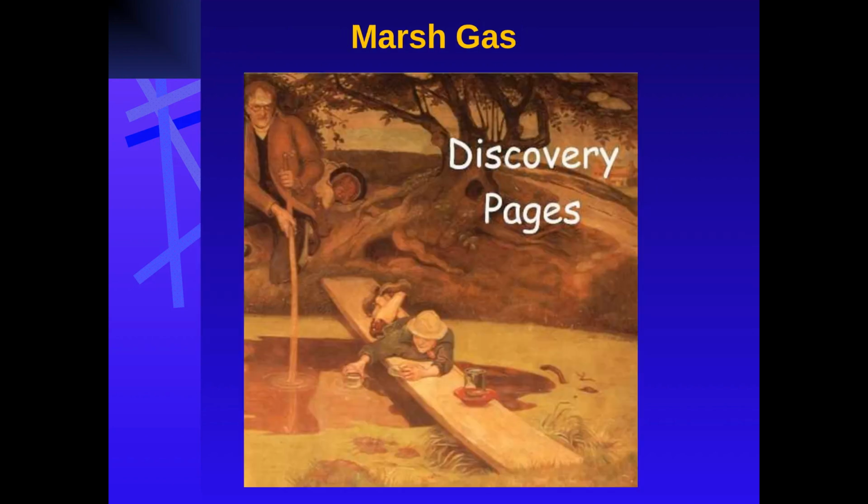Aerobic treatment, while effective, has several disadvantages. It is an energy-intensive process, primarily due to the need for continuous aeration. It also produces large volumes of sludge, which requires further treatment and disposal, adding to the overall operational cost. Moreover, aerobic systems can be sensitive to fluctuations in organic loading and may not be as effective for treating high-strength industrial wastewater.